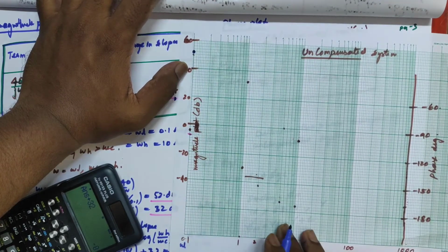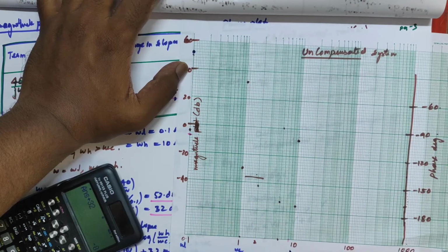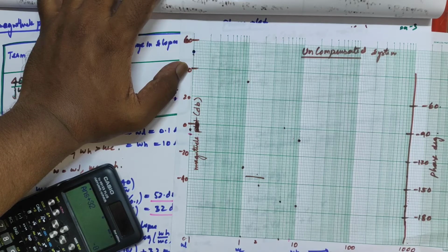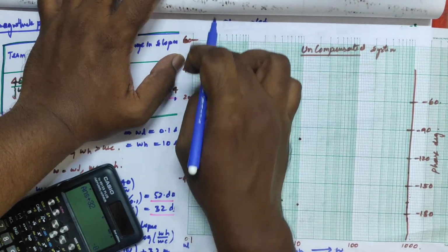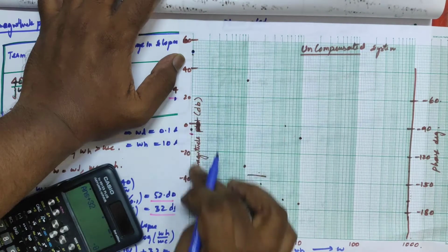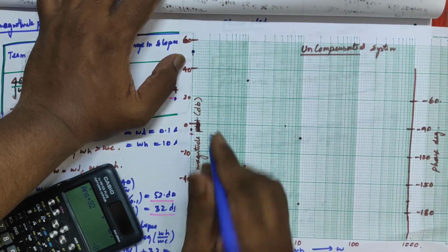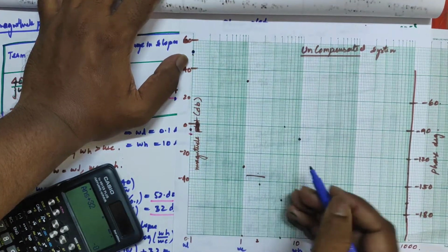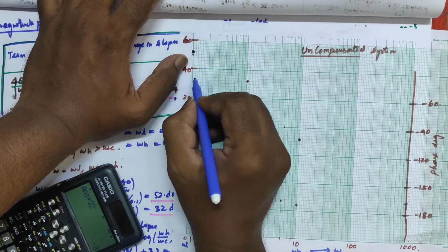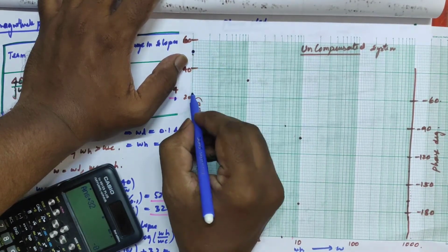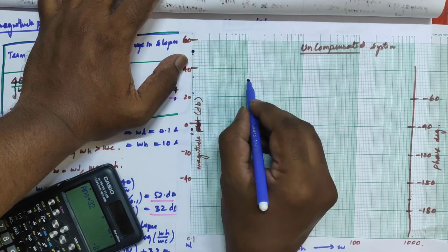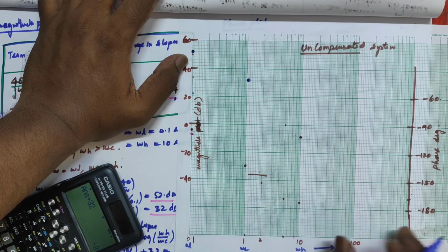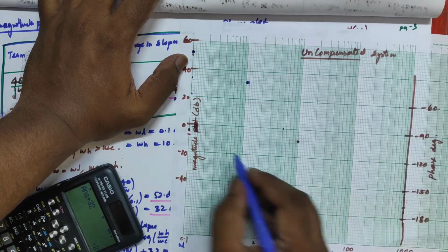Now this is omega c, and this is omega h, and this is my omega value varying. At omega L I got 52. On the y-axis for magnitude I marked 0 dB, 20 dB, 40 dB, 60 dB, so 52 is obtained here. At omega c I obtained 32. Each division is 2, so here I'll have the 32 value. At omega equal to omega h, the higher frequency, I have the minus 8 value.